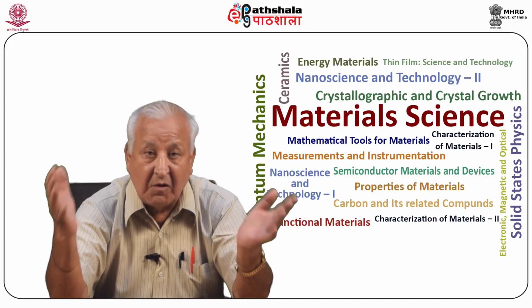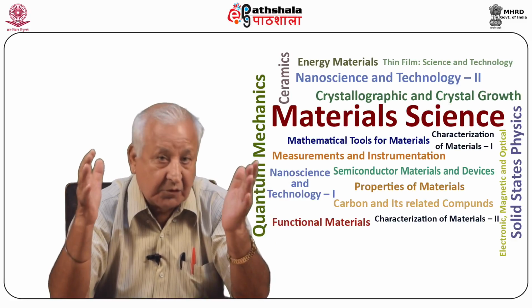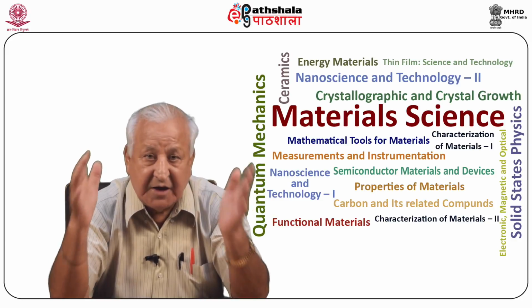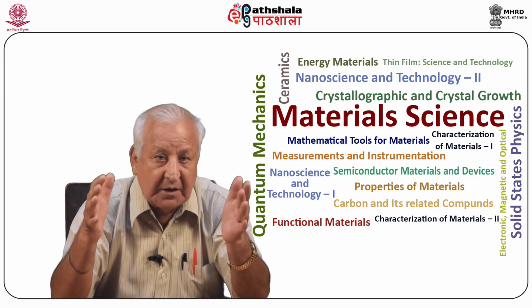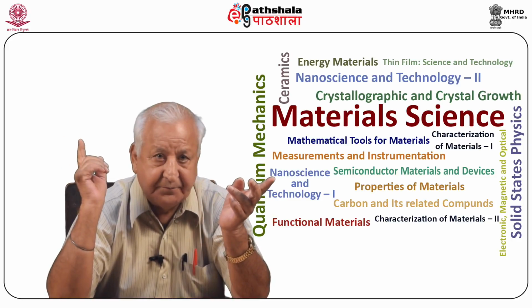Well-faceted crystals are formed at the bottom and or walls of the crucibles. The crystals are separated from flux by gently hammering the crucible and then cleaned in 10 to 20% HNO3.